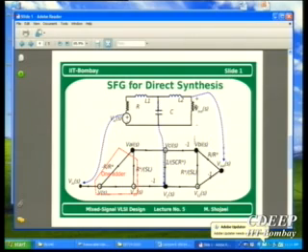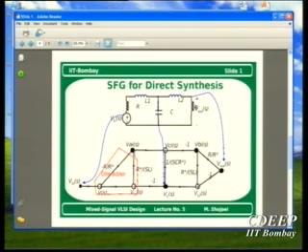If you notice, we had three components, and purposefully I wrote the equations in such a way that everywhere we will have an integrator. Therefore, the voltage of the capacitor will be a function of its current, and the current in the inductor will be a function of voltage. Multiplying current by some value will convert it to voltage. We call it R star, and then accordingly we get the signal flow graph.